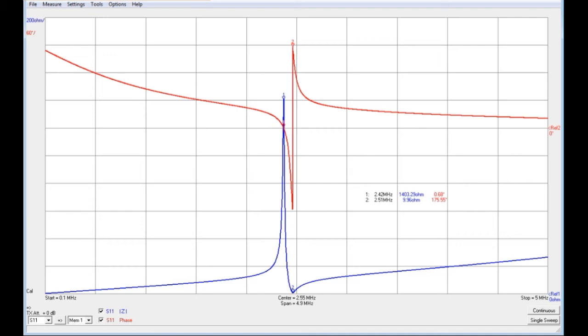that we see, this is how the generator would actually drive it. So the frequency that this coil would be resonating in this mode, provided that the generator was tuned to match it, it would resonate and oscillate strongly at 2.42 megahertz. So this point here, if I was to use something like a vacuum tube oscillator with feedback on it to drive this, then it would automatically self-resonate at that point,